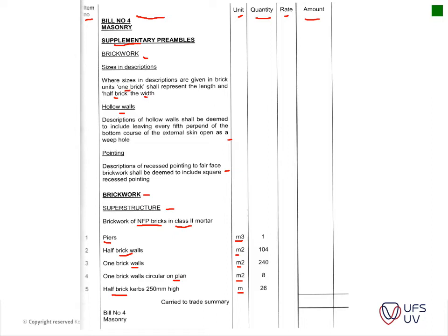measured in length. So the main thing you want is a combination of information. For instance, here they included the height, so the contractor knows how high it is, and then he's given a length, so he can easily calculate how many layers of bricks he needs for this length of construction. So the main thing is the contractor should have a complete picture of how he's going to measure or price, what he should allow for